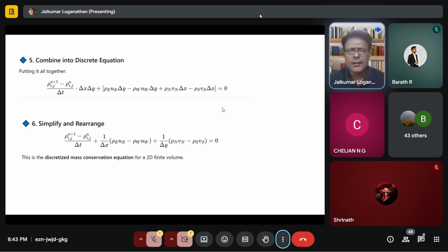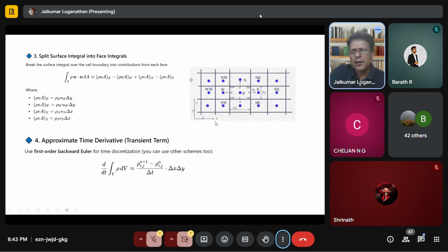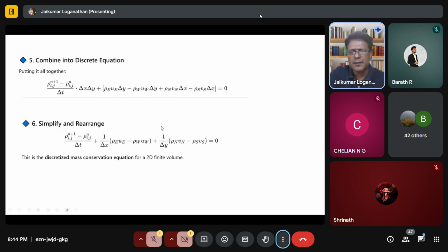Okay, okay. Yeah, I think slowly you'll be learning this, but try to visualize what's happening, right? Because if you just look at the equation, it doesn't really make sense. You'll only try to memorize this and then write it on the exam, right? But try to visualize what's actually happening. What does the mass conservation mean? What does the momentum conservation mean? And how, on a given mesh or grid, do you discretize that? Once you get that basic, it becomes a cakewalk to look at all the rest of the equations.